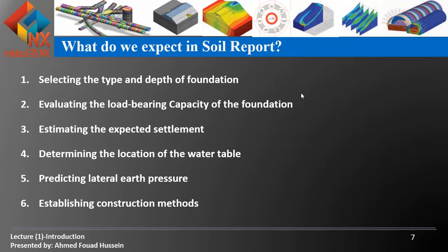And if we have a deep foundation, like piles, we have to calculate the capacity of the pile, either in bearing or friction. Then we have to calculate the expected settlement regarding the loads, and then determine the location of the water table and predict the lateral earth pressure coefficient, like at-rest earth pressure.